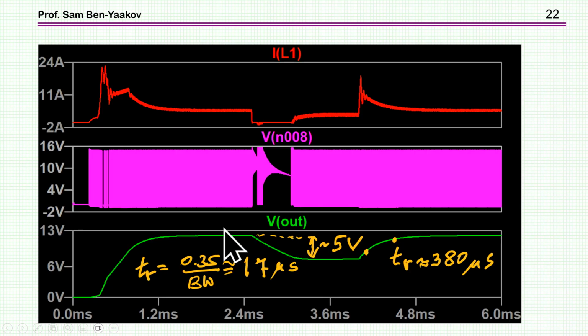And here is what I see. This is just the startup of the converter, okay? And here we have the two cases, the one injection in one direction, another injection in the other direction. This is the inductor current, and this is the midpoint. So what we see here is, as I inject a positive current into the junction and the voltage has to go down, we see a very slow slope here.